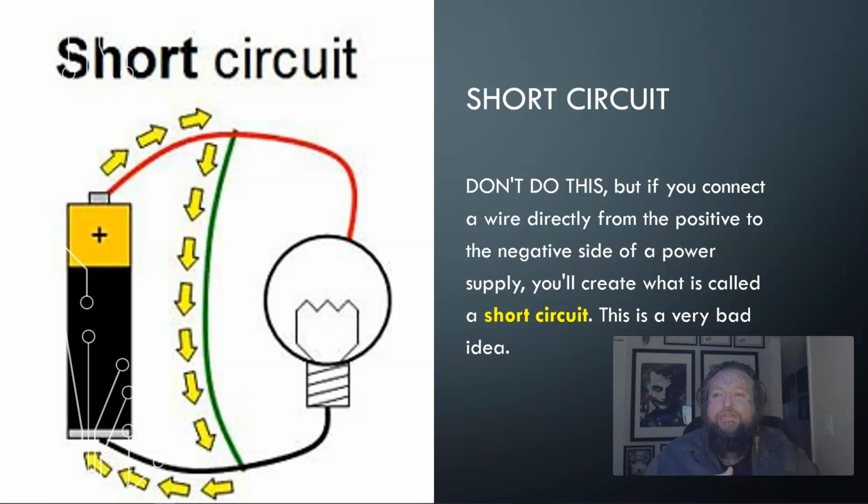This also matters when you're creating circuits and connecting things together. If you have a circuit and a path, and two pieces of metal are touching at all, that will allow the flow of electricity. Even if they're really close, if the voltage is high enough, those electrons will jump. Our circuits are going to be weak enough that that won't really happen, but if it is high enough, you have to worry about that. So you usually want to have insulating material in between, because if anything starts touching, it's instantaneous. That short circuit, things could blow up, your circuit's not working properly. You need to check for this and be careful. Even when you're touching things and it's on, that can also have problems. And if you've got this hooked up later on with the Arduino and your computer, you want to be careful what could go on.